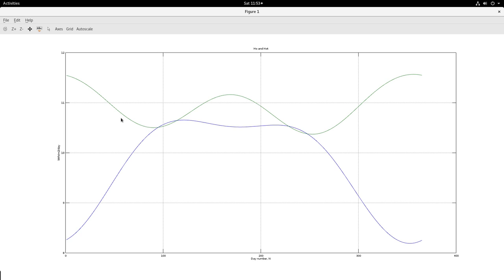So this is the benefit you would get by tracking it on a daily basis, but it is cumbersome to track because you need to fit motors and mechanical arrangements, which you have to pay for. So in order to keep it simple, people generally have a fixed angle tilt and try to optimize on the fixed angle tilt which you would place. The other option is to have seasonal tilt. So every season, let us say 3 times or 2 times in a year, you can change the tilt angle and keep it and maximize the energy that you collect over the year.